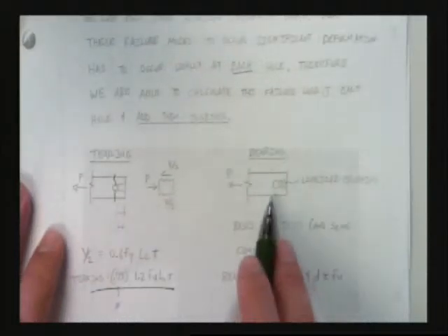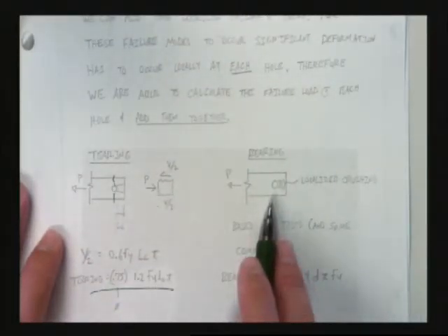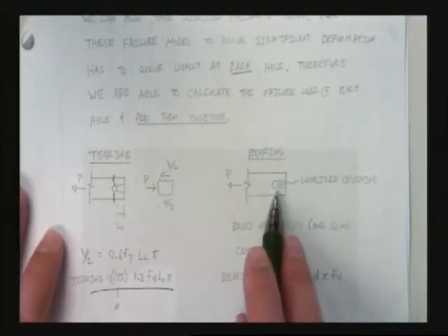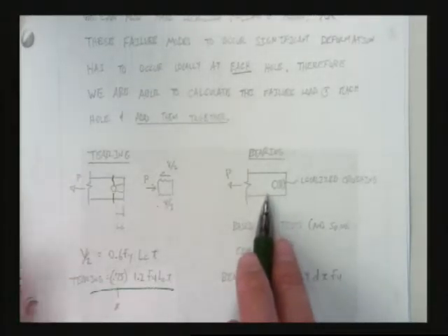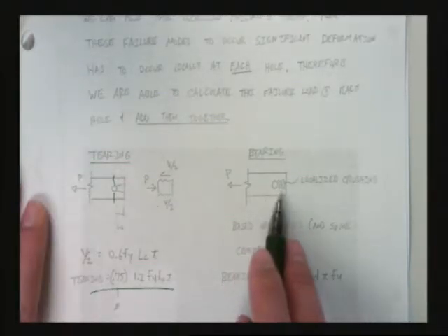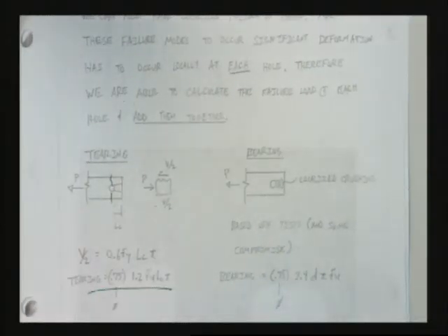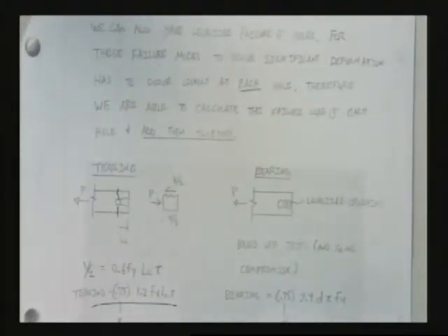And then there's this thing called a bearing check. This idea that, you know what, I'm going to move these holes way away from the ends, but for whatever reason, my plate becomes small, really, really thin. What will happen is you'll get localized crushing and buckling. And I'll show you a movie. I don't think I have time to show it today, but I'll show you a movie on Friday of both of these happening.